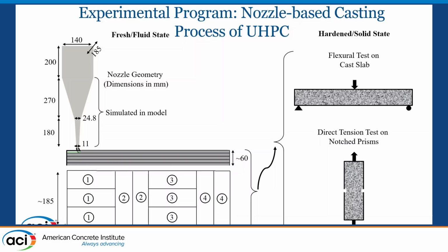So we want to connect this fresh fluid state UHPC with the hardened solid state. We want to identify fiber orientation in this experiment. We want to feed that data to the solid mechanics model so that we can predict the capacity of this slab. We can also predict the direct tension behavior just from the fresh state flow.